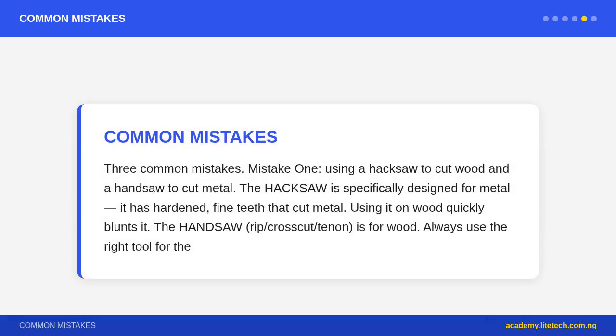Question 2. Explain the difference between a ripping saw and a crosscut saw. A ripping saw cuts along the grain of wood, or parallel to the fibers. It has larger, fewer teeth with a cutting action like a row of chisels. A crosscut saw cuts across the grain, perpendicular to fibers. It has smaller, more teeth that slice the fibers like a series of knife cuts. Using the wrong type produces a rough cut and requires more effort.